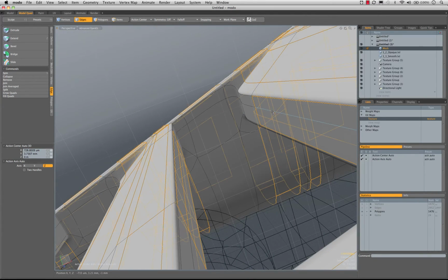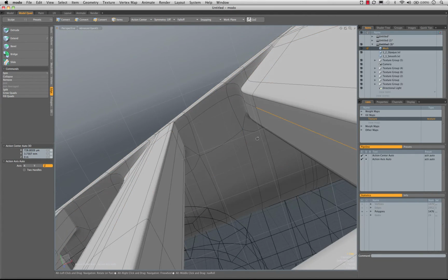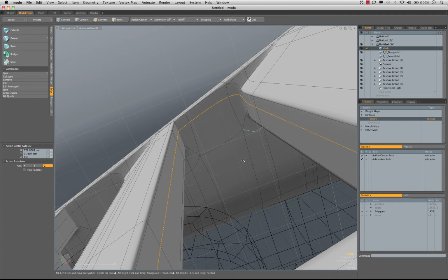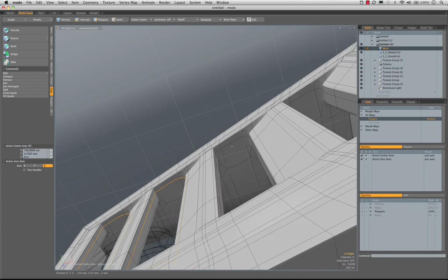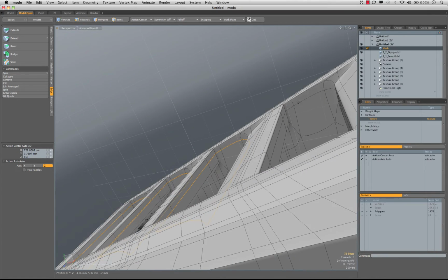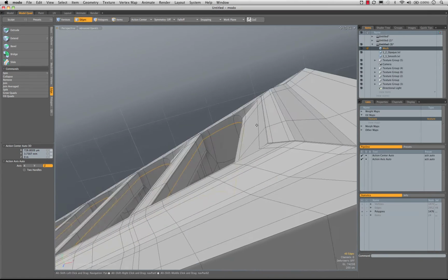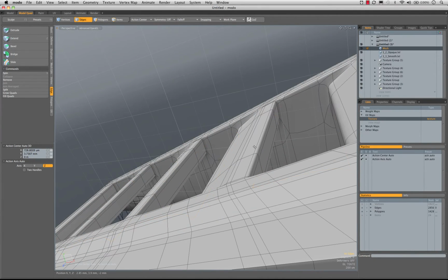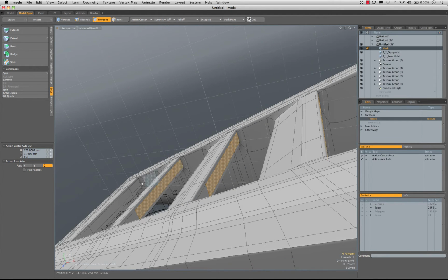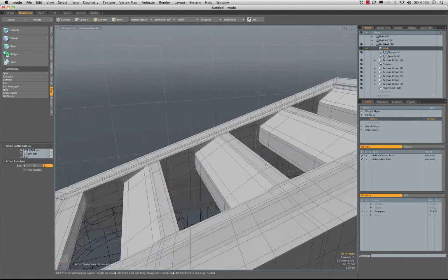And actually we'll probably want to run one down the middle of here. So what I'm going to do on each of these is select this middle edge here. I'm going to get rid of this and replace the whole thing with a double loop slice. It will give us more definition on our geometry. So let's delete those. And then I'm going to grab this, this, this, and this. I'll run our loop slice through there.